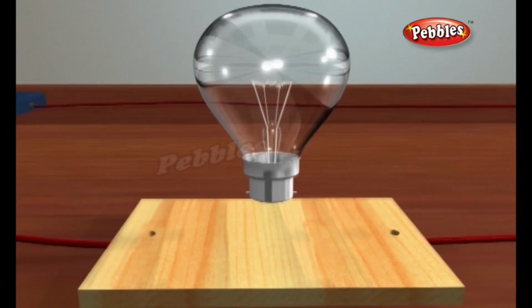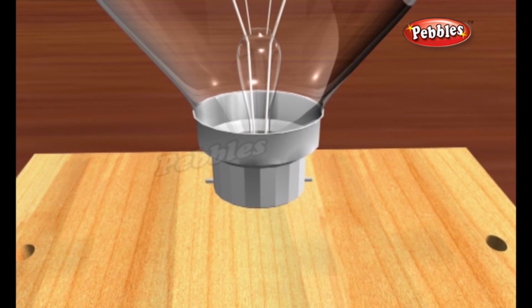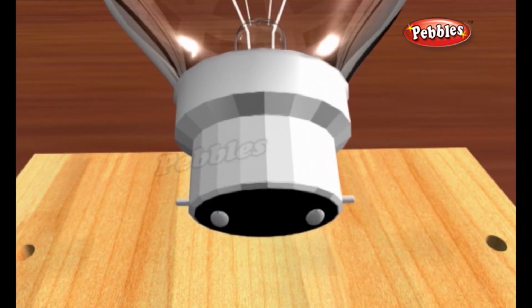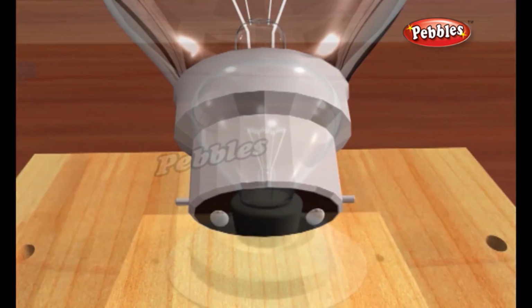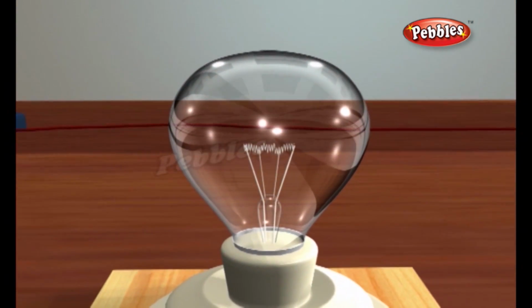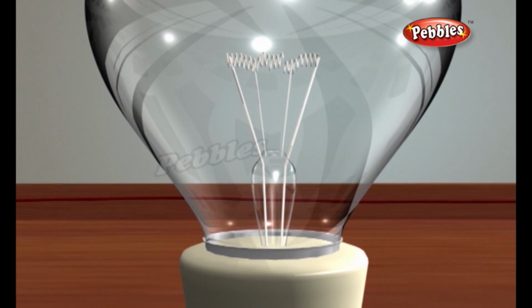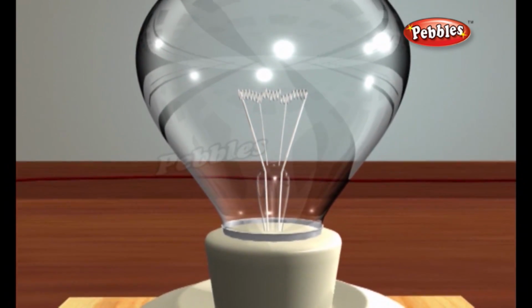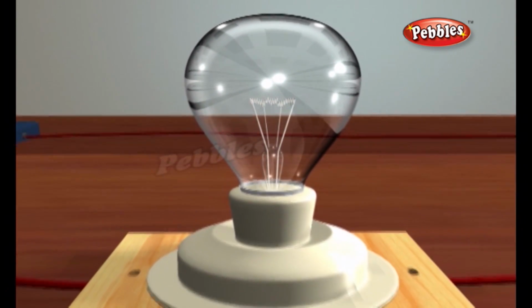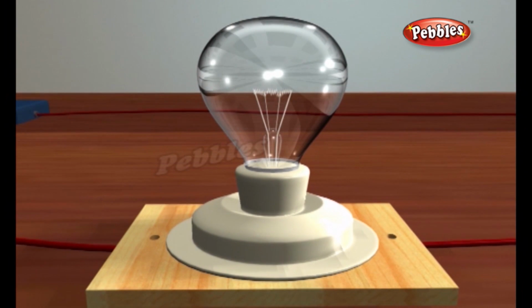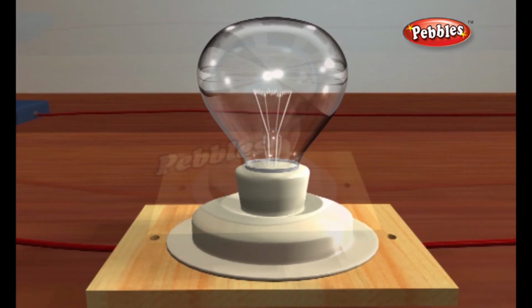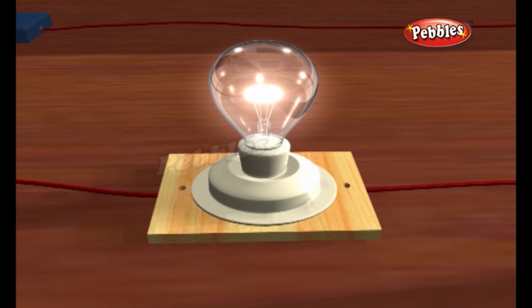Light bulbs have a very simple structure. At the base, they have two metal contacts which connect to the ends of an electrical circuit. The metal contacts are attached to two stiff wires which are attached to a thin metal filament. The filament sits in the middle of the bulb, held up by a glass mount. The wires and the filament are housed in a glass bulb which is filled with an inert gas such as argon. When the bulb is hooked up to a power supply, an electric current flows from one contact to the other through the wires and the tungsten filament.